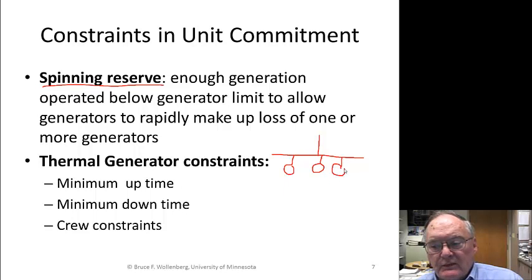Now with the 3 generators that we have here, no, we can't do it. So let's just go to a hypothetical 4 generator system, and I lose a generator that was generating some amount. Once that happens, the governors want to bring this unit up, and this unit wants to come up, and this unit wants to come up, and I need this much space.